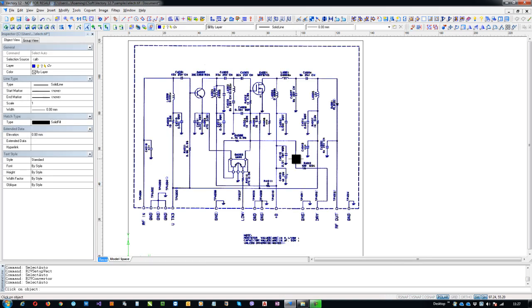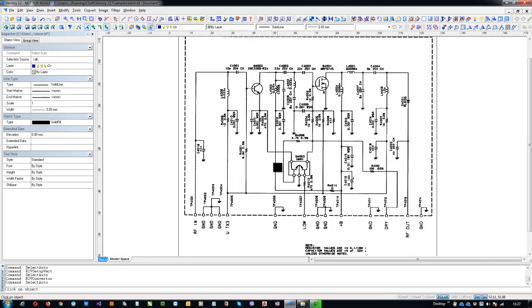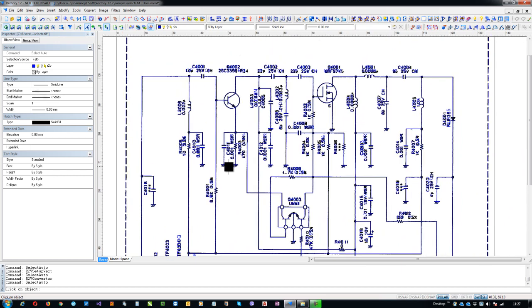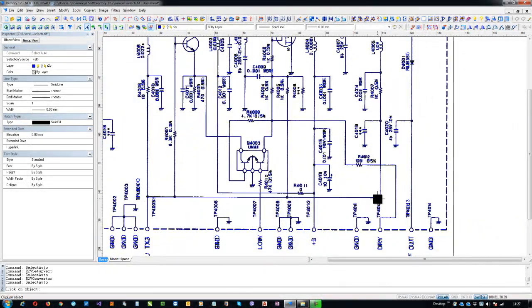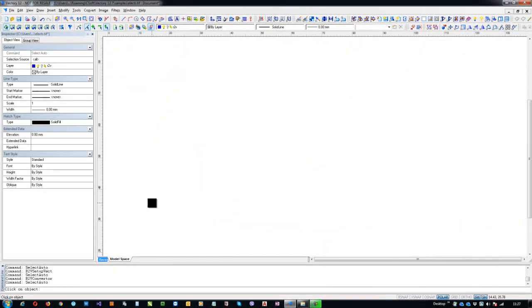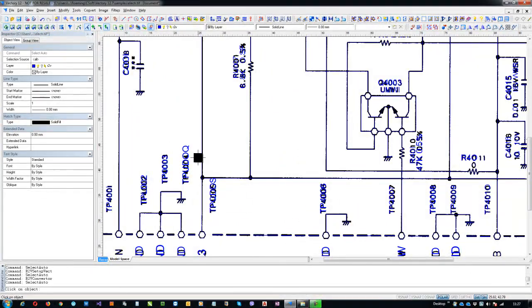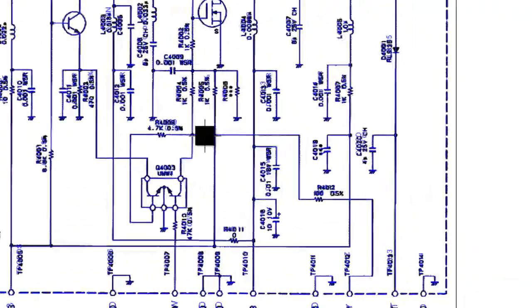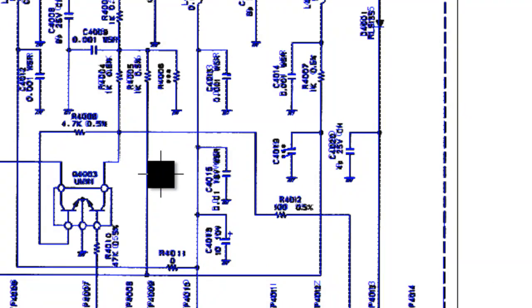So if I click, most of the entities of this electrical drawing will be converted into CAD, and all the symbols will convert into CAD, right? A few of the symbols, if you have, unfortunately, not converted during this method, you can always go back and set or update the symbol library a bit, and then you can come back and convert the whole thing again. And now you can save this result as a DWG or DXF.